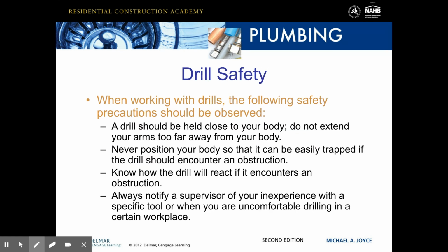When working with drills, the following safety precautions should be observed. The drill should be held close to your body. Do not extend your arms too far away from your body. Again, this goes back to safe tool handling procedures. Never position your body so that it can be easily trapped if the drill should encounter an obstruction.